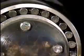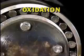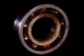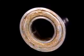Corrosion can also come from acids produced by lubricant oxidation. Oxidation occurs when a lubricant combines with oxygen, and it tends to occur more rapidly in equipment that operates at high temperatures. The acids produced by oxidation can corrode equipment and lead to lubricant leakage. Besides forming acids, lubricant oxidation can form harmful deposits on metal surfaces. The varnish deposits on this bearing came from oxidized grease.